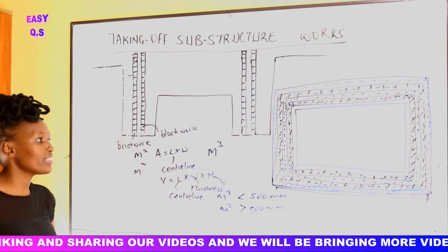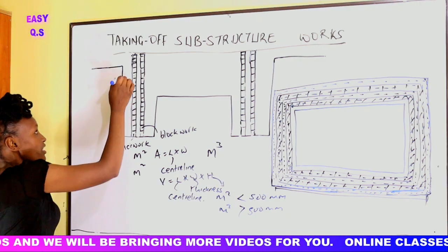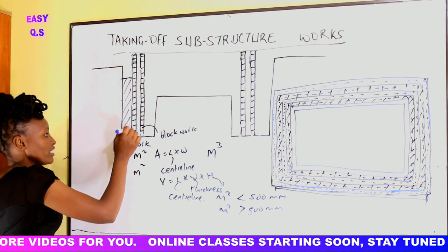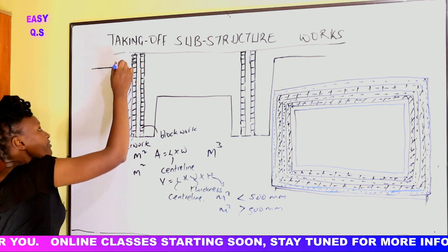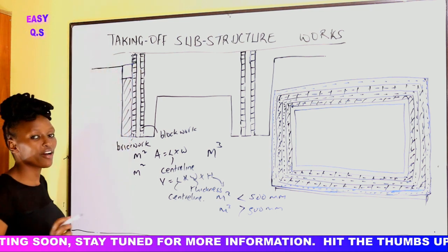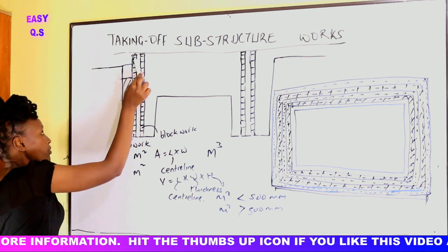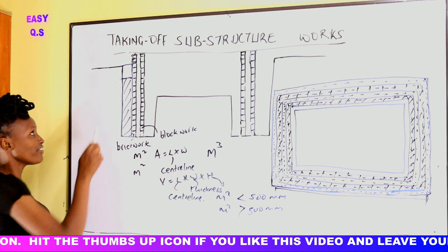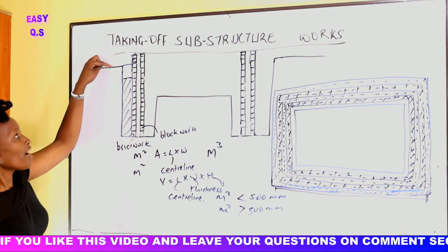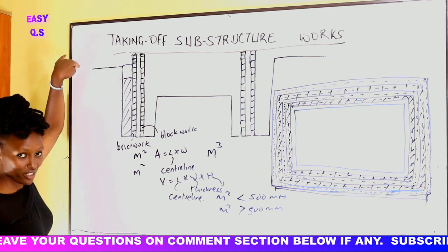Alright? Okay. So the next item after reinstating the soil up to this level, we have already returned the soil up to this level. We haven't filled it up to the ground level. Assuming we backfill the soil up to this level, that means that between the house and the rest of the ground, we shall leave a hole. And because that is not normal, we need to backfill the vegetable soil that we had removed so that we can go back to the ground level.